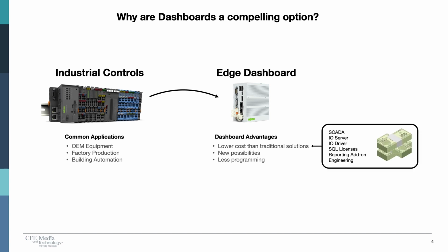Traditionally, we would look at deploying a SCADA system, I should say. These carry with them costly licenses in many cases. You've got to have a server to run all this software. There's usually a lot of add-ons and then all the engineering that goes into the programming of these complex SCADA systems. We're really just not after a complete SCADA. We're really only interested in logging data. It's more of historical reference for things that are happening on the plant floor and generating alarms when needed. These typically require a lot less programming. They're a little more configurable and easier for operators to analyze the data compared to complex SCADA systems that require a lot of custom training.